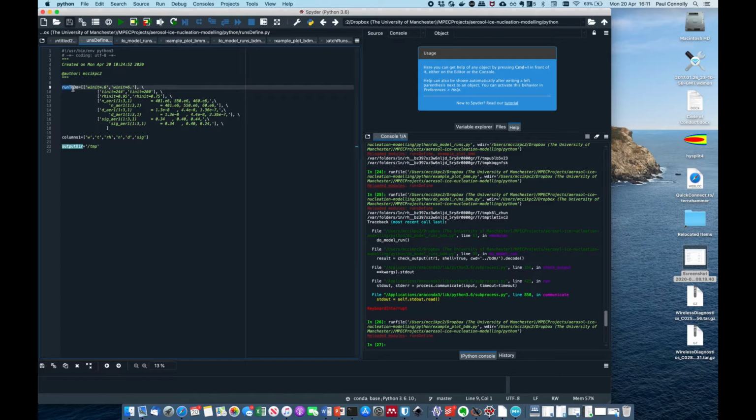And this runs to do shows us a list of simulations, and here we have a list of 6 types of simulations: 1, 2, 3, 4, 5, 6, and each type of simulation has 2 possible values. So the first one, W init, that's for the vertical wind. That's how fast the air is moving upwards in the parcel of air that we're simulating. So that goes from 0.6 meters per second to 6 meters per second.